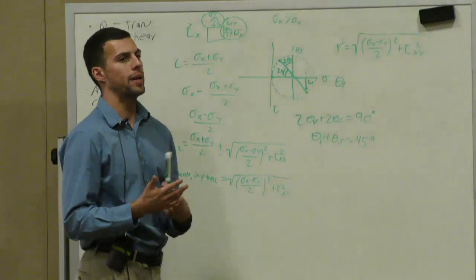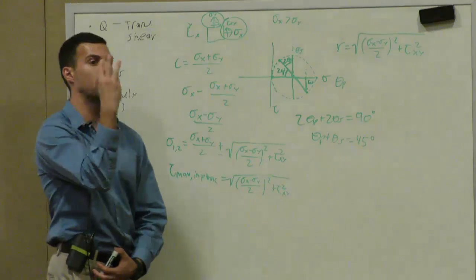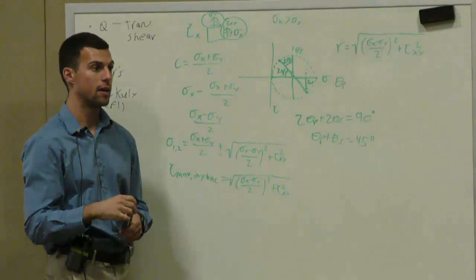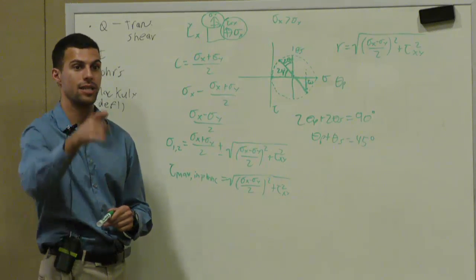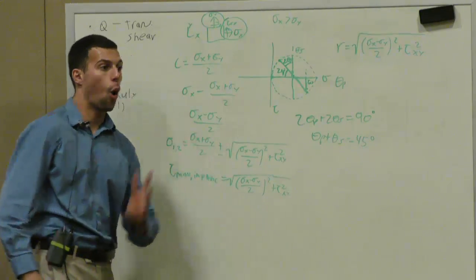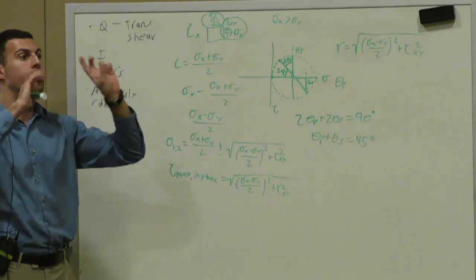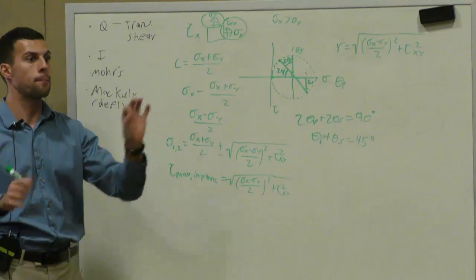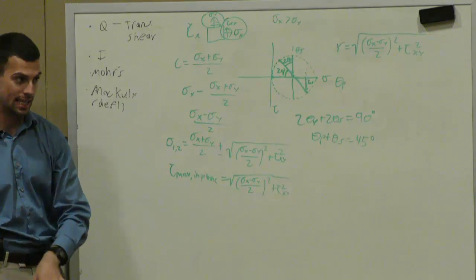So what ends up happening is, in planar stress conditions, you actually have three principal stresses. The two that we calculated here, and what is the third one? Somebody said it. I heard it. 0. Your third principal stress is always 0. Note, your third principal stress is always 0, not principal stress subscript 3 is 0.